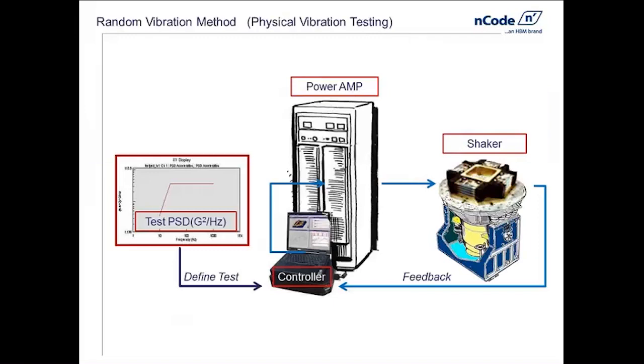times we have to qualify those with a random loading, and we do that on a test rig that is an electro-dynamic shaker table. To do this, we program in a random signal. It may be acceleration, force, into our shaker table, and what will happen is it will generate a random loading representing that PSD, let's say, of acceleration, and apply it to our part. And the qualification test will be so many minutes, hours, days of excitation with this random loading.